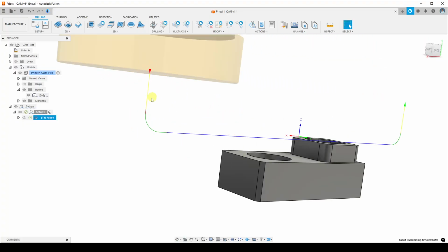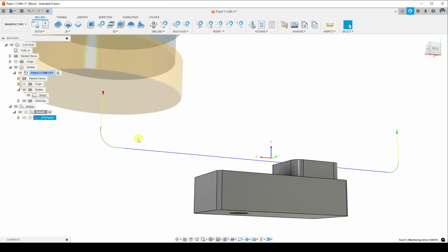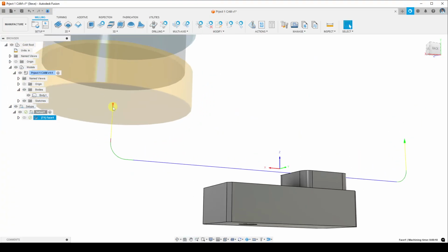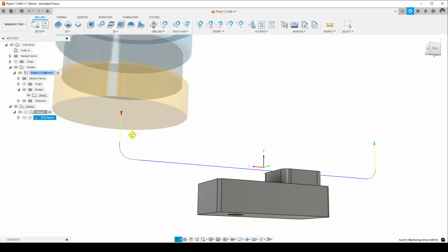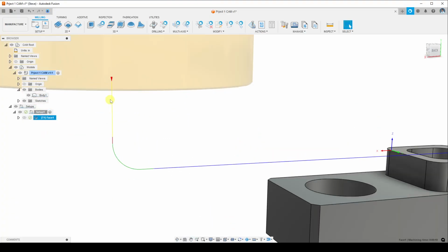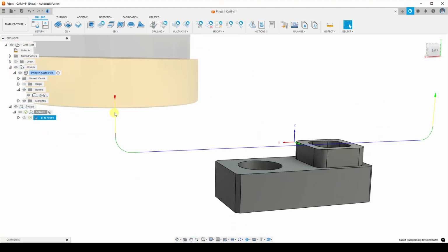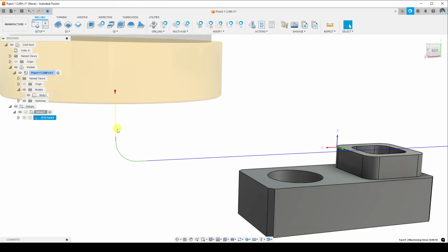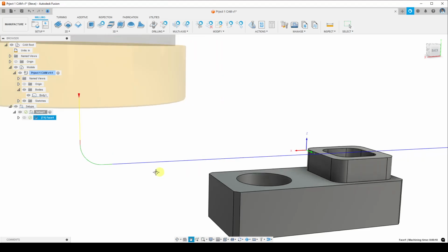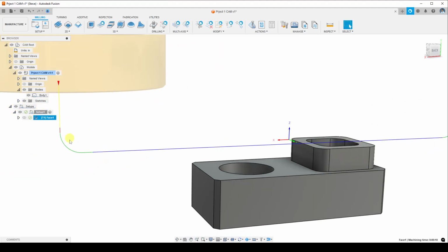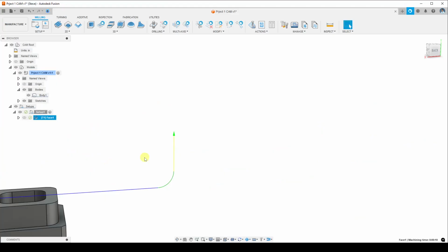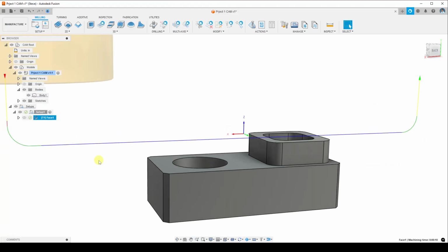The line is where the movement or the position of the center at the end of the tool is, and where it's going to move. The different colors of line mean different things. Yellow means it's a rapid movement, like a positioning movement. Red is like a ramping movement. Green is a transition, like a lead in or a lead out. So it's like getting into a toolpath or getting out of a toolpath. And then blue is the cutting.